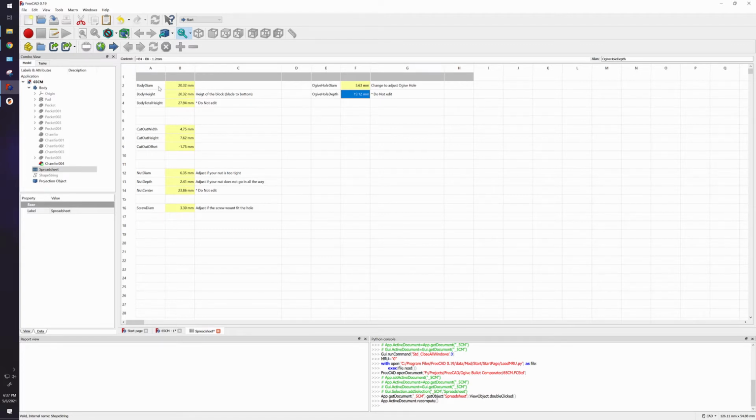However, if you find that you want a bigger height, my height is set at 0.8 inches. This is because my end stop is 0.2 inches, and that gives me 1 full inch, which makes it very easy to use with the dial caliper. If you're using a digital caliper, don't worry about changing this.